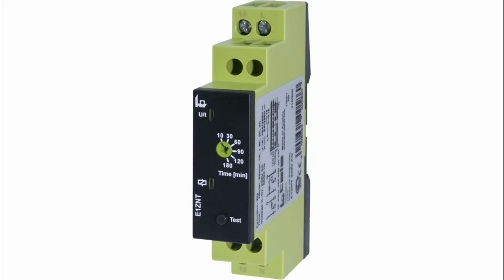For example, on-delay relays are commonly used for motor starting applications to prevent rapid cycling. Off-delay relays are useful in applications where a device needs to remain powered for a certain period after the control signal is removed, such as in conveyor systems. Interval delay relays find applications in sequential timing operations, such as traffic signal control.